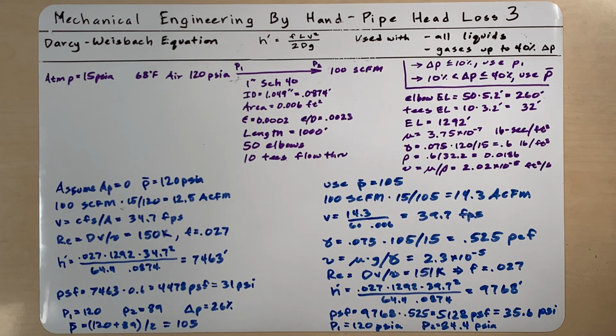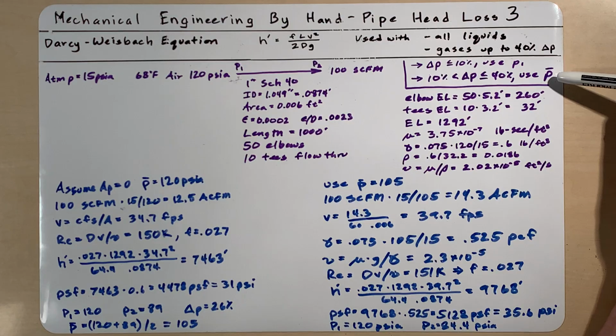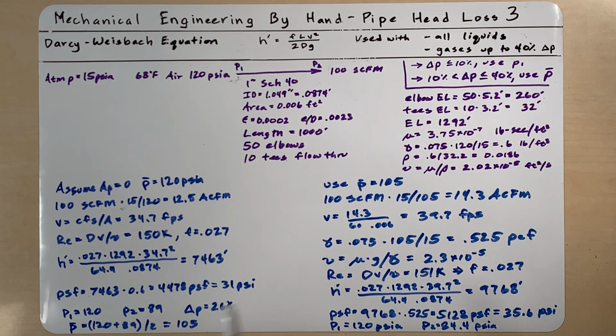So now this pipe, if this were installed in a plant, would have way too much pressure loss. You'd probably want to go with 5% or less. The only time I can think of a pressure loss being this high would be an overland transport pipe, but that's not going to be made of 1-inch pipe.